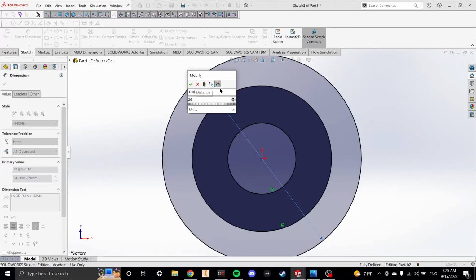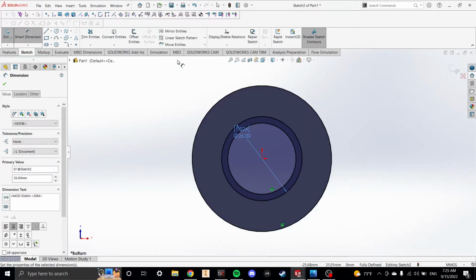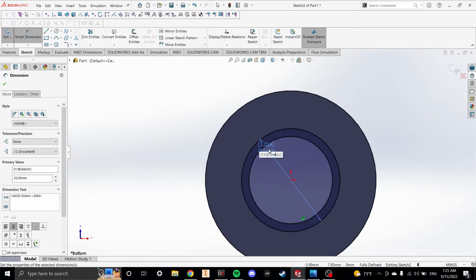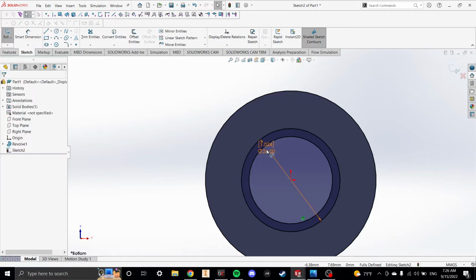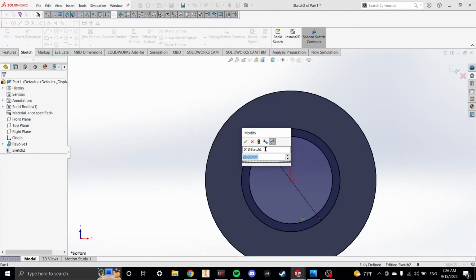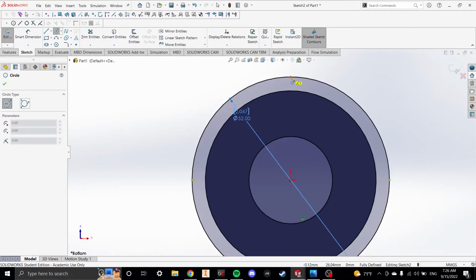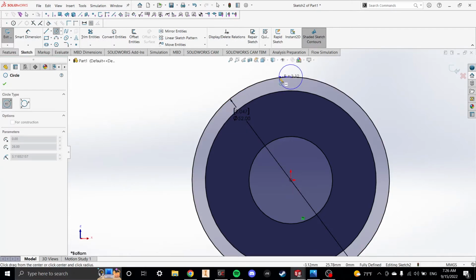And this is where I'm going to be putting some circles on to make the spaces for those holes. Oh, sorry, radius of 26. So 26 times 2 is 52 millimeters. There we go. And we're just going to add a circle on here. And this circle is going to have a radius of 6.